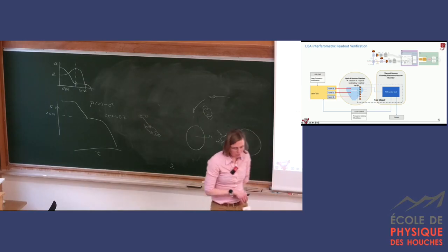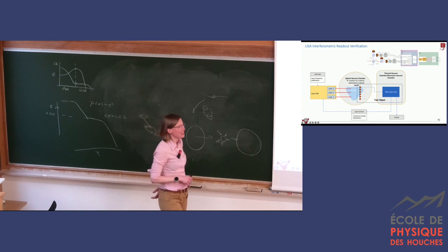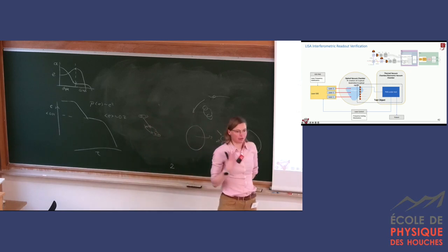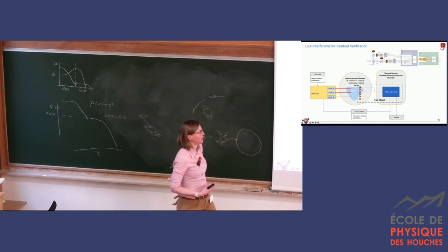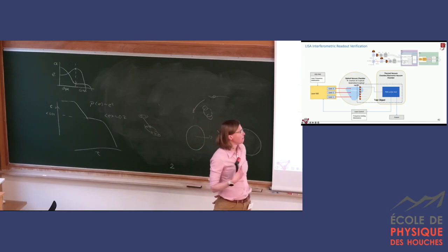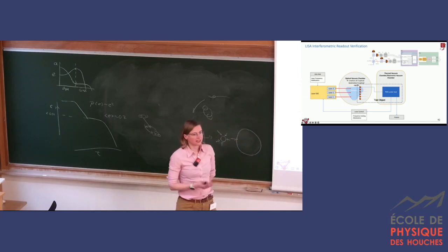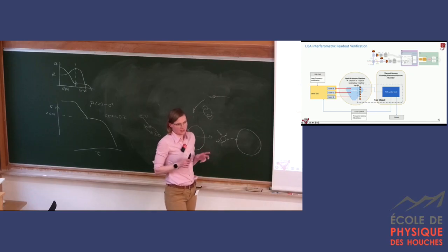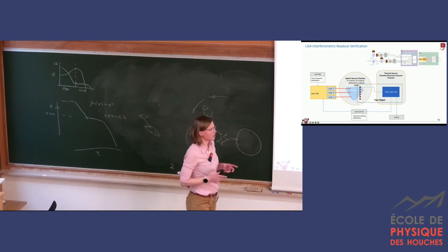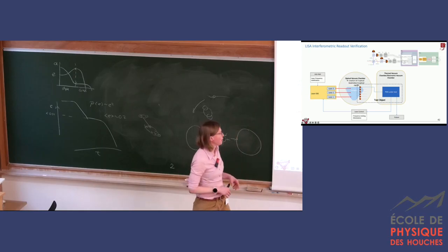And now the second important thing, I tortured you a little bit with the phase readout system and DPLLs. We need to ensure that our readout system really works, right? And works as we expect and provides all of the functions. For that, we are developing a dedicated test setup, which is called Hexagon, because it has 6 beam splitters and tries to mimic 6 links. Such that we can exchange PRN codes, we can exchange timing signals, and actually verify that everything works within the noise level that we allocate.